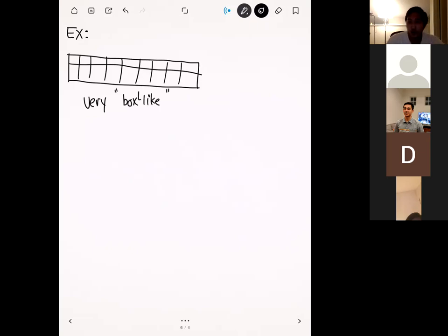And the opposite of this, where a hexahedron wouldn't work, would be something with a lot of curved edges. The most extreme case for this would be a sphere. A sphere is the quintessential curved surface, which doesn't have any sharp corners or any corners at all. So something like this, a hexahedron would probably really struggle to mesh. For something like this, you'd have to mesh it with tetrahedrons.